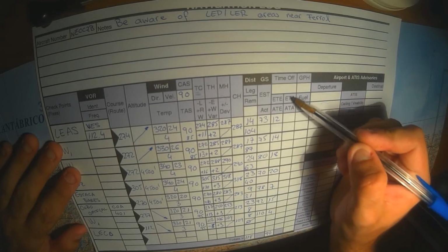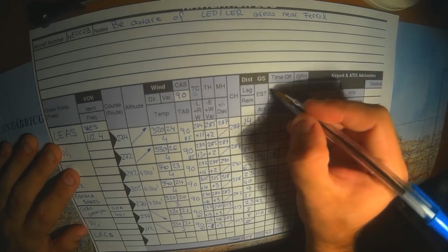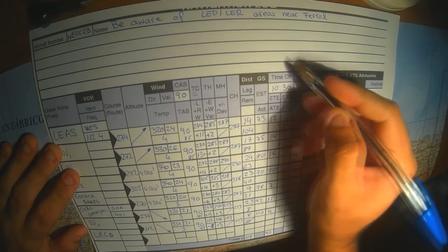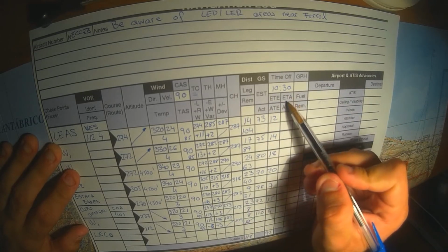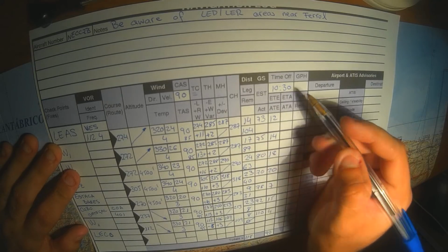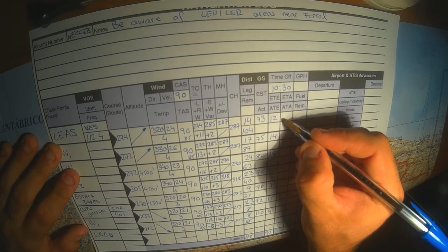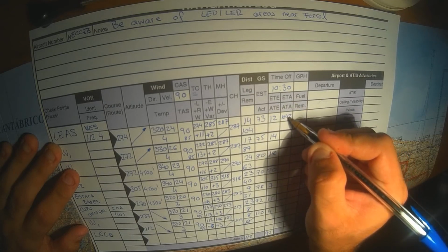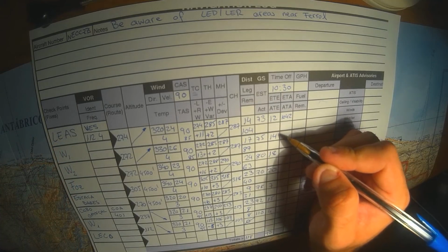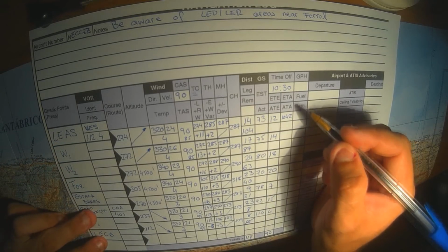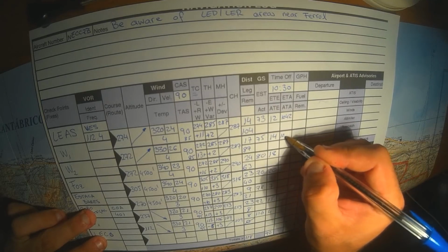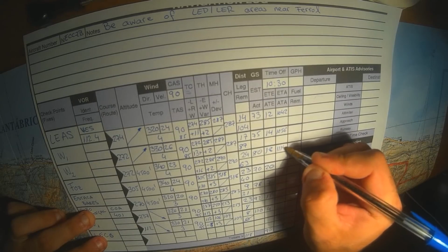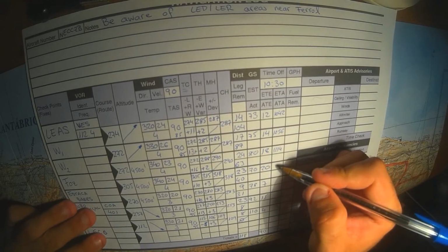Next column of time is the estimated time of arrival to a checkpoint. Let's say we depart at 10:30 in the morning and we want to know at what time we expect to arrive at each point. This is as simple as using the ETE we have just calculated before. Departing 10:30 plus 12 minutes of flight to the first checkpoint gives us an ETA of 10:42. We're supposed to be over Whiskey 1 at 10:42, plus 14 minutes of flight to Whiskey 2 gives us an ETA to Whiskey 2 of 10:56.